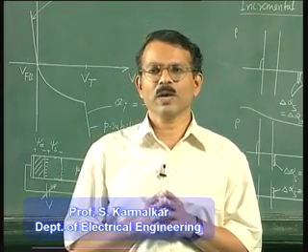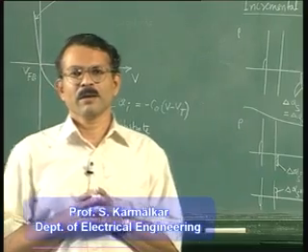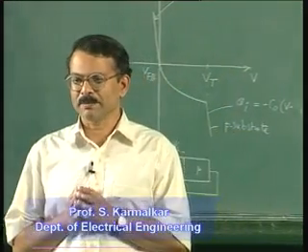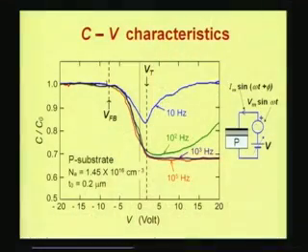Now if you look at the capacitance voltage diagram here, experimental characteristics, you will find the behavior of the capacitance shown by the blue line corresponds to low frequencies. Now here you do not see a very abrupt change of the capacitance, okay, this is gradual. Now this is because the frequency is not low enough.